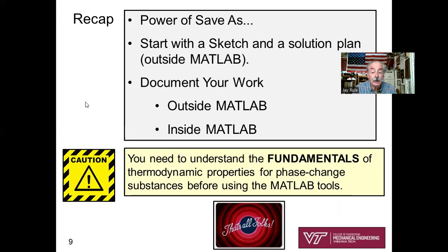It's hopeless to go right from manager's question into MATLAB. You've got to start with a sketch. You've got to draw something down on pencil and paper. You have to have a solution plan in your head, and maybe have some pencil and paper work off to the side as you do your MATLAB solution. So document your work outside of MATLAB. That's the sketch and the plan. And inside MATLAB, use lots of MATLAB comments, starting with that % sign.